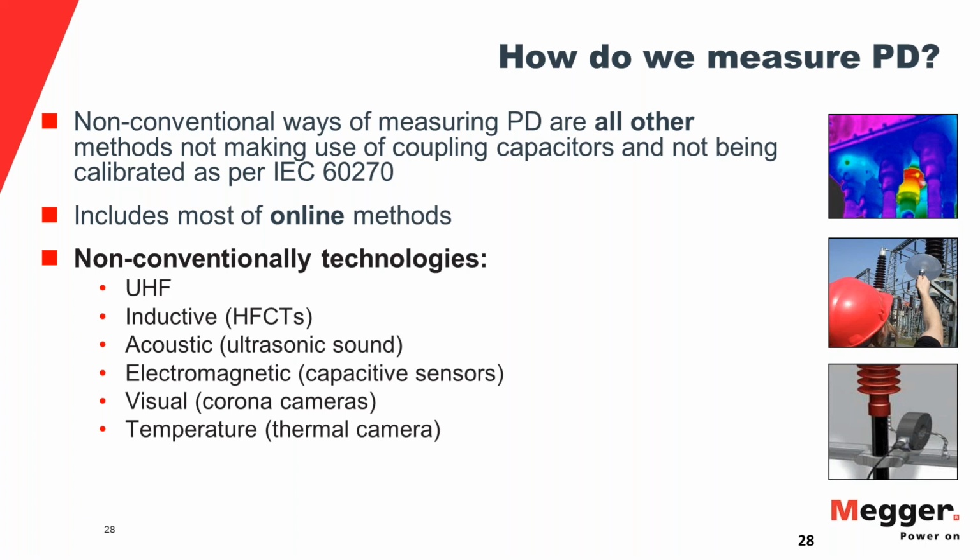You cannot calibrate the circuit because you rely on operating voltage, so it's kind of a warning system. You gain yourself a little bit of time just before the catastrophic failure to take action, but you don't really see the condition coming, because you cannot vary system voltage to 1.7 times or something like that to see if there's a condition coming up and growing.